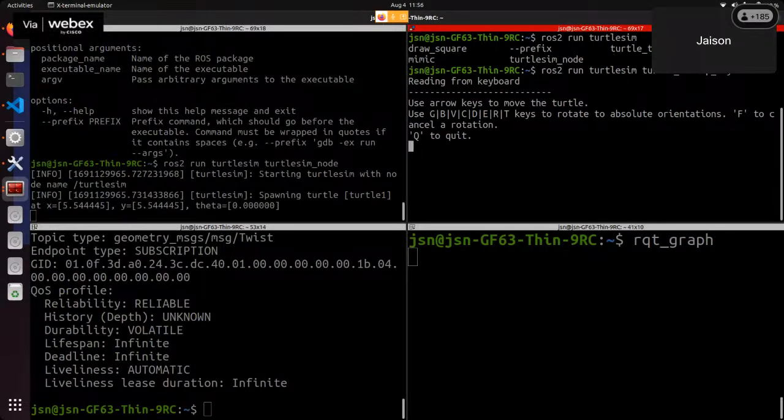And when we did double tap, it also suggested what nodes are present inside this. All this information is inside the setup.bash. And how does the terminal know about setup.bash? Because we have written it inside bashrc. Before the terminal opens up, it executes everything inside bashrc, and then our terminal starts. That's how it gets to know where the packages are and what the contents inside a package are, right?